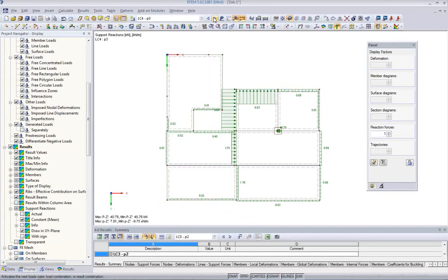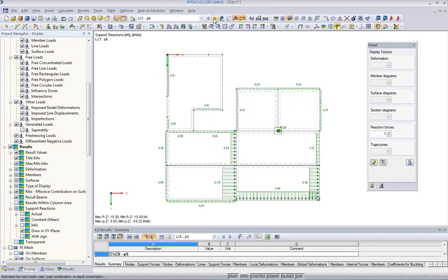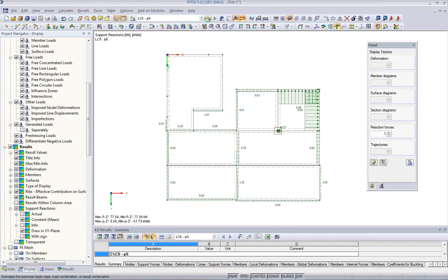So what we do is we integrate all the support forces along the line and average them to a mean value. This is a good way how you can maybe use this information also for a load on the next story that you have maybe below.